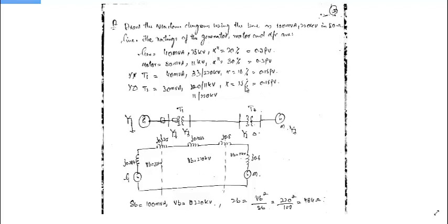Usually you will see that all the transformers are always written high voltage to low voltage, whether it is connected from the primary side low voltage and then on the secondary side high voltage, but it will always be written like this. But here, for your convenience, I have written 33 by 220, that means here will be 33, here will be 220, then 220 by 11, that means this side will be 220, this side will be 11. So I hope you understood this.